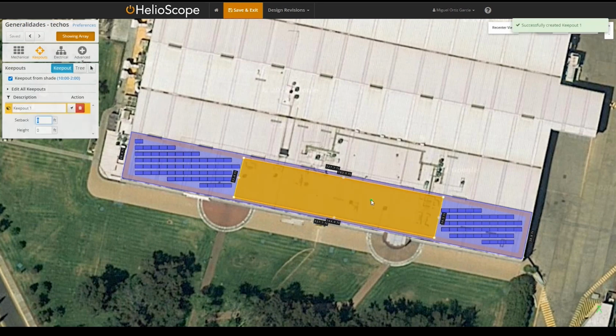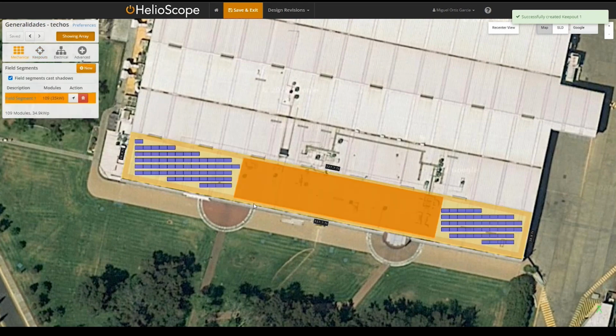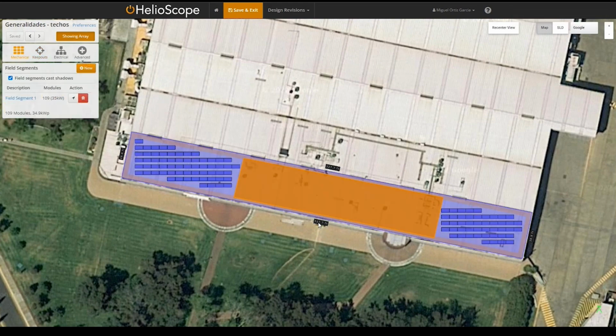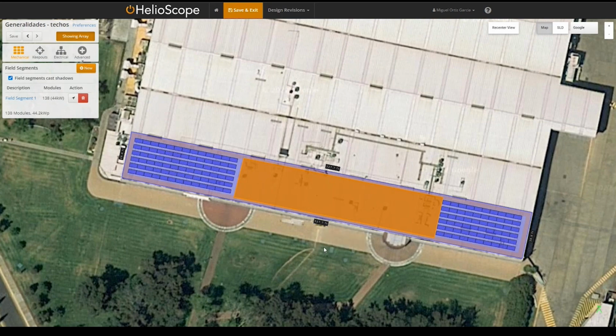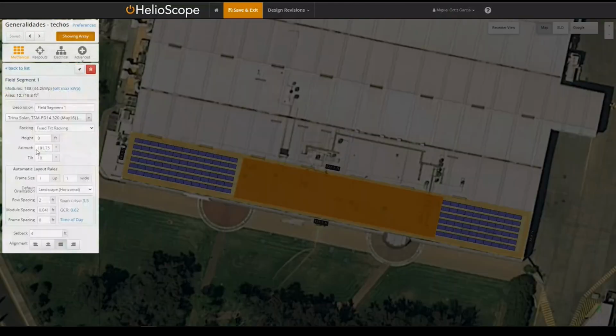Select the side of the roof where you want to align the modules by right-clicking on the dimension box and choosing the Set Azimuth option. Always use block-like alignment to ensure proper import into Base.